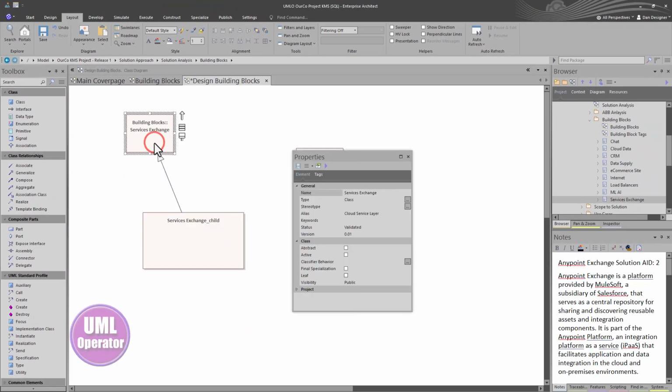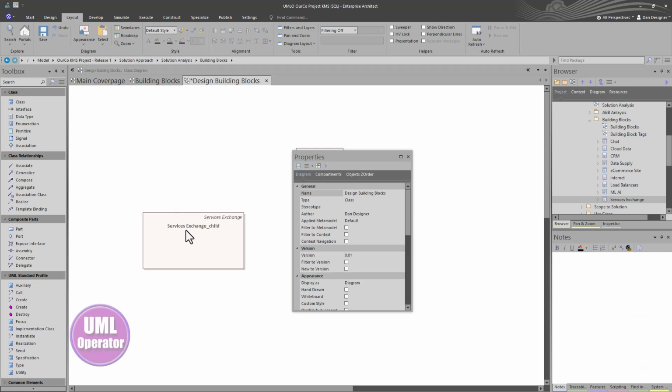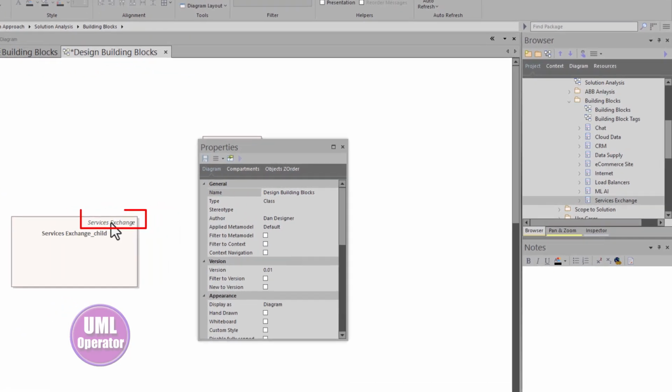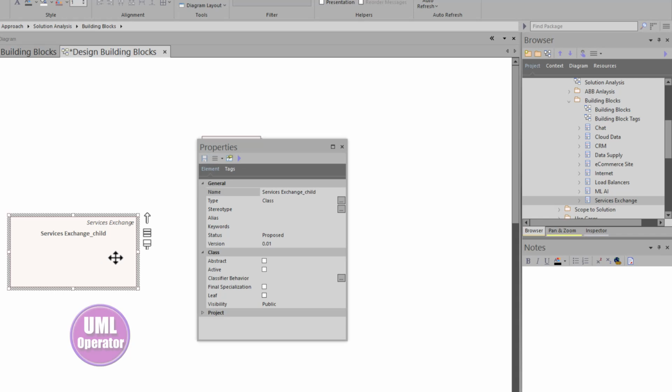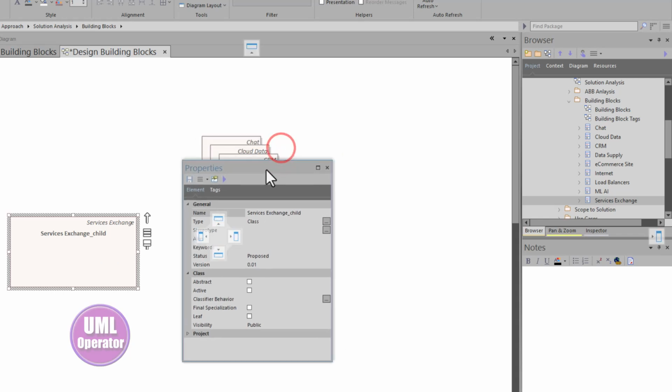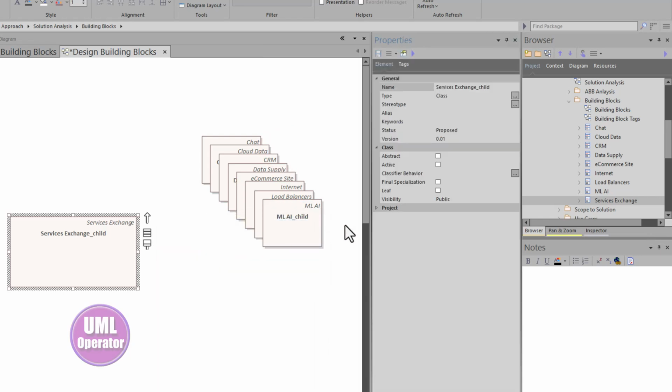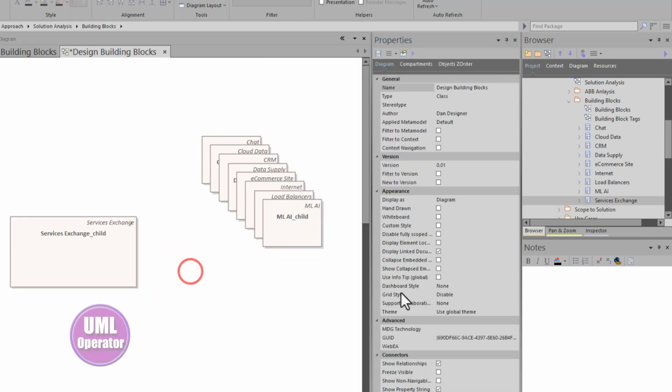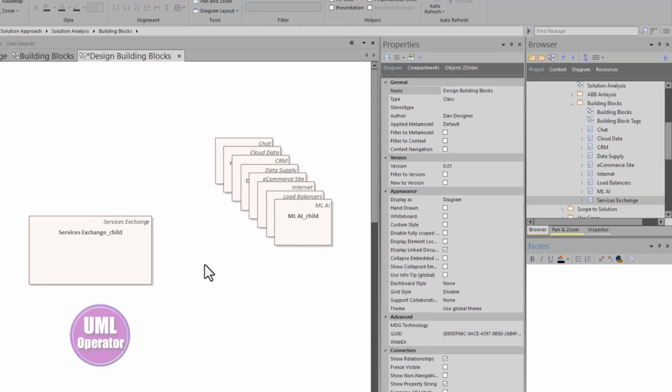And then we're just going to go ahead and delete the superclass from the diagram. And you can see as soon as we did that, we pick up in italics on the upper right side the superclass name. So we have a blank element that we can start using and working with. So what I like to do is take properties and just put it to the right of the diagram. I have my notes in the lower right as I move properties here. And let's start organizing these.